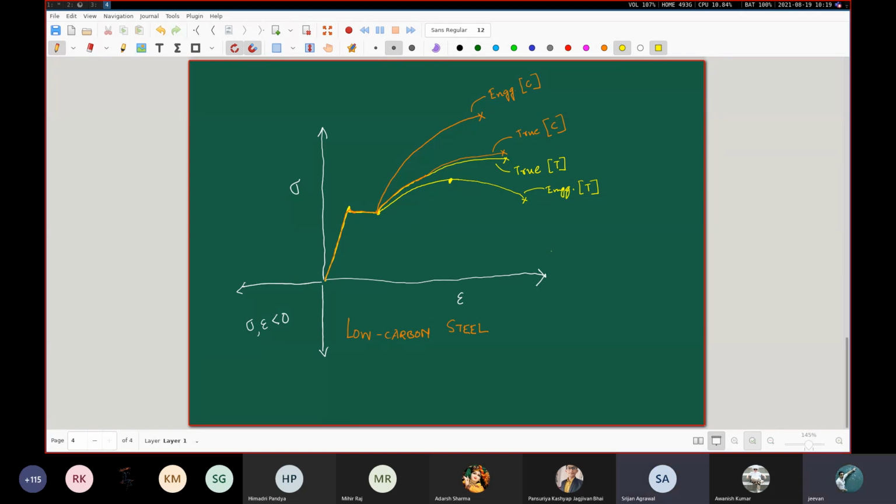So see, whether it is the tension case or the compression case, you have to understand very concretely the loading which is applied. In the actual experiment, some kind of weights are placed, and the value of these weights is the same. In fact, the entire experiment is the same. It's just the data points generated for the true stress, true strain diagram versus the engineering stress, engineering strain diagram that are different. So the only difference lies in the consideration of the area.